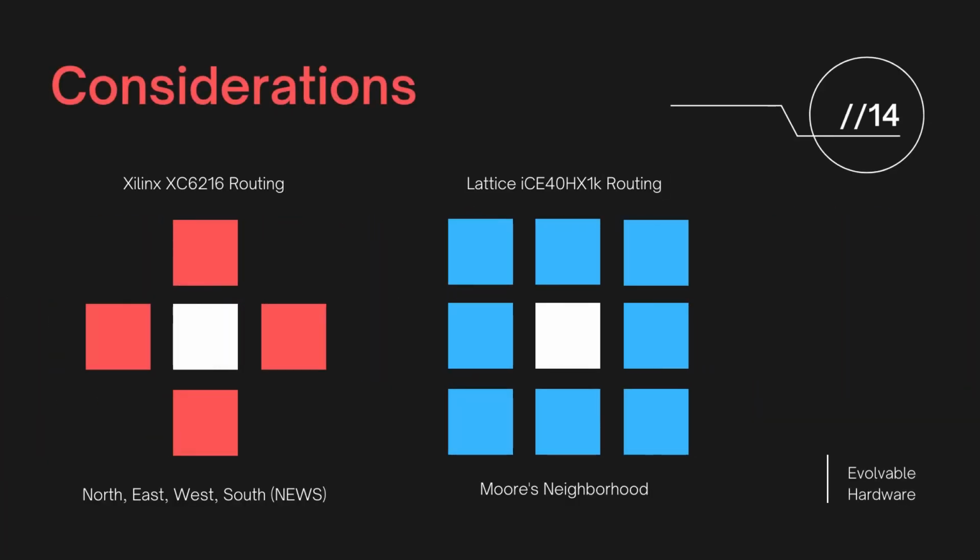But before getting started there, it's an important technological difference to note between FPGAs used in past evolvable hardware experiments and those available today. Modern FPGAs have made over 2 decades worth of advancements and contain highly sophisticated signal routing mechanisms and very dense logic capabilities. To avoid creating an overly complicated routing interpreter, while still attempting to mimic the routing and logic used in Thomson's experiments as closely as possible, we implemented local routing in the form of Moore's neighborhood.